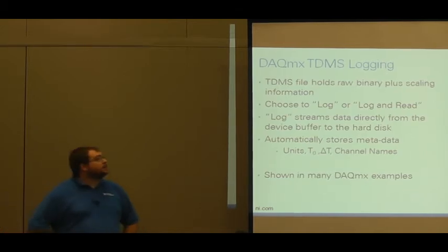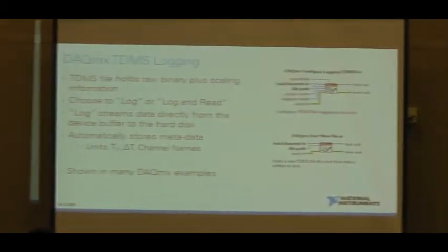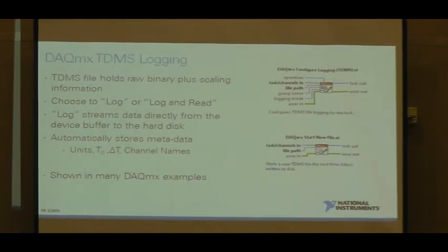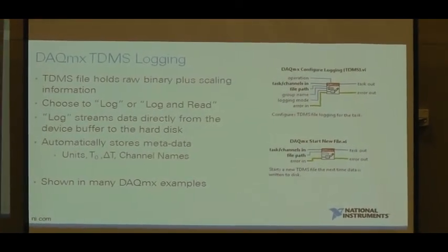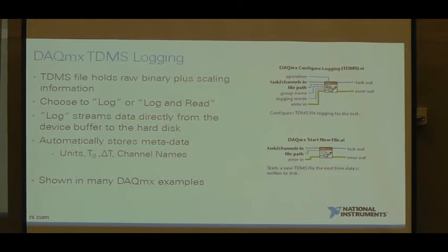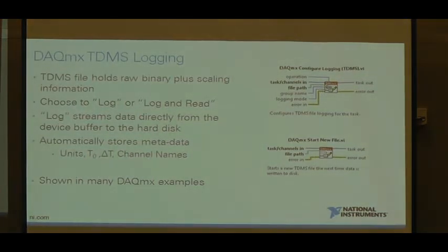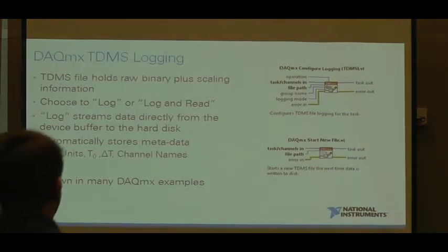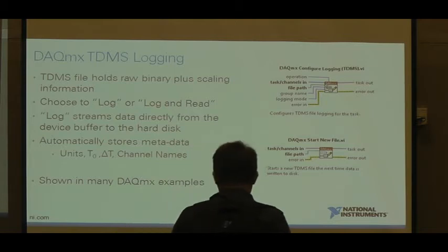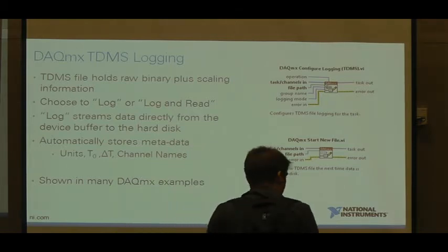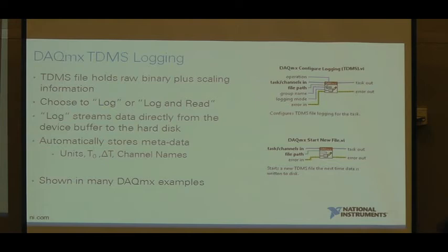So the next topic is DAQmx TDMS logging. Many of you may have used TDMS files before, but I've found many customers aren't aware that a DAQmx task will log directly to the TDMS file. No need for you to set up a producer-consumer or use the ExpressVI to log the file. You can drop down the DAQmx Configure TDMS Logging, pass it a file path, and we will stream data directly to that file.